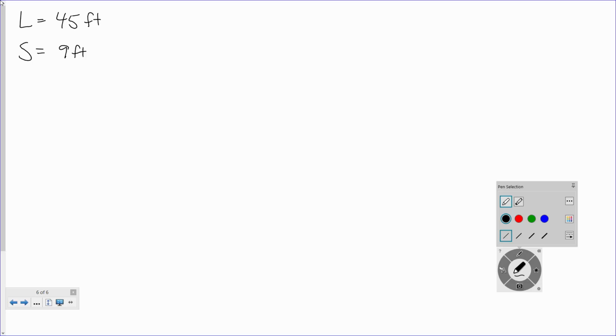Okay. Now, if you recall that KLL, that's a live load element factor. It's the ratio of the tributary area to the influence area. Okay. Now, are we looking at a column or are we looking at a beam? Beam. So what's KLL? 2. All right? So let's keep going.